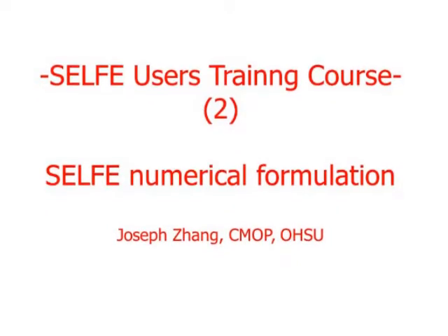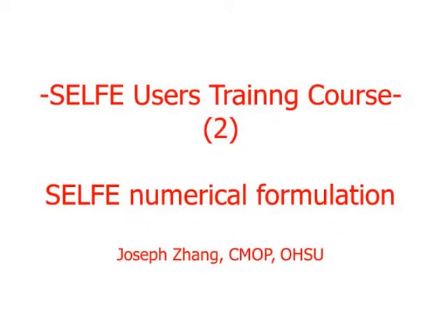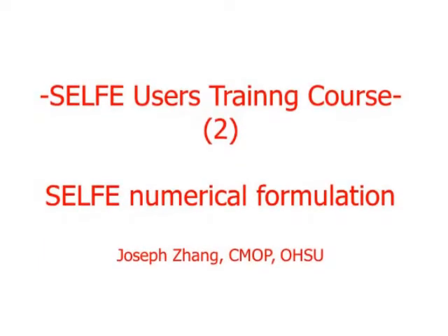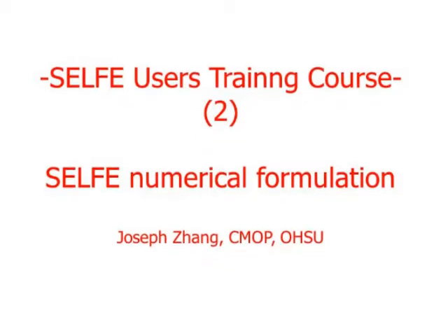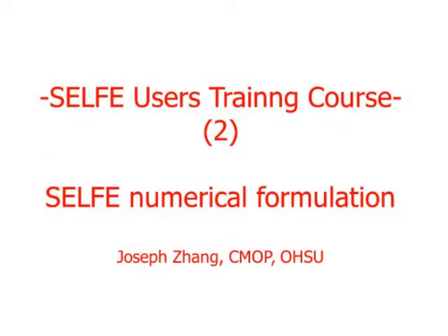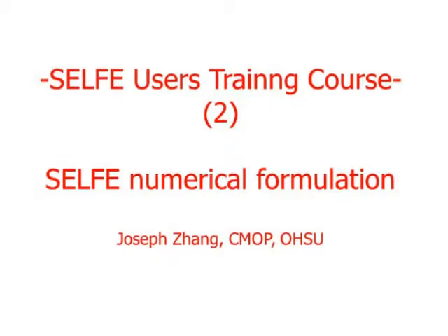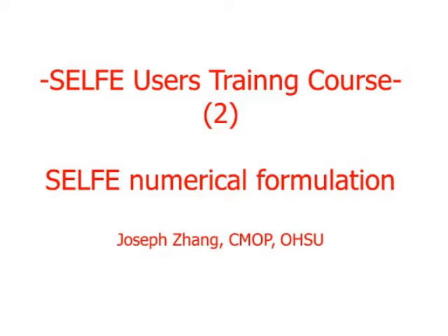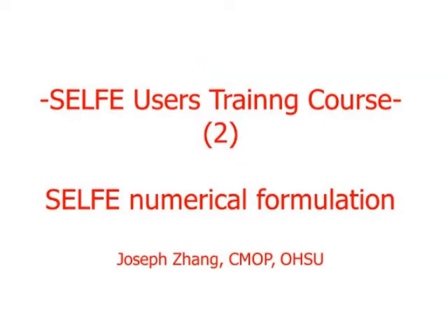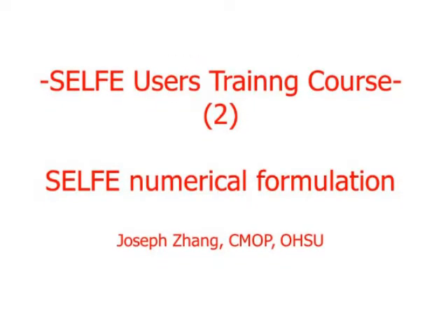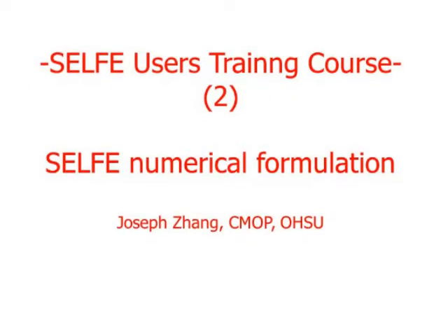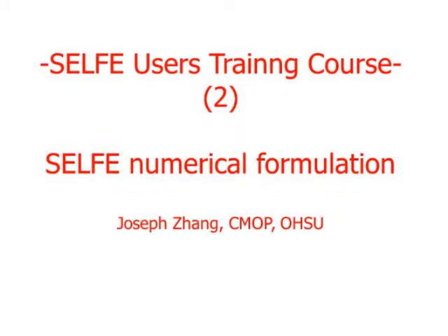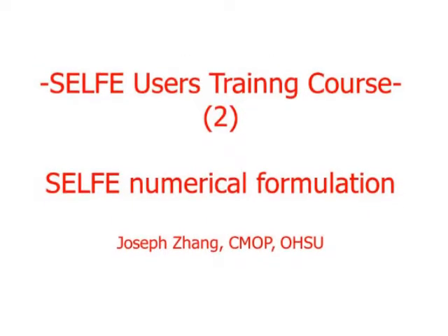Okay, next slide, number 11. So let's apply the standard Galerkin weighted residual weak statement for this first equation, the continuity equation, discretized in time. Then you integrate by parts. That's the essence of weak formulation. Then you get a bunch of boundary integrals coming out, gamma. And you further divide the boundary into two parts, depending on whether you have an essential boundary condition or a natural boundary condition. So you get gamma and gamma bar.